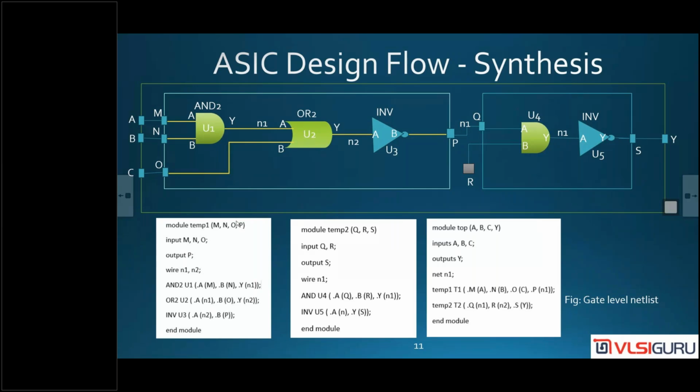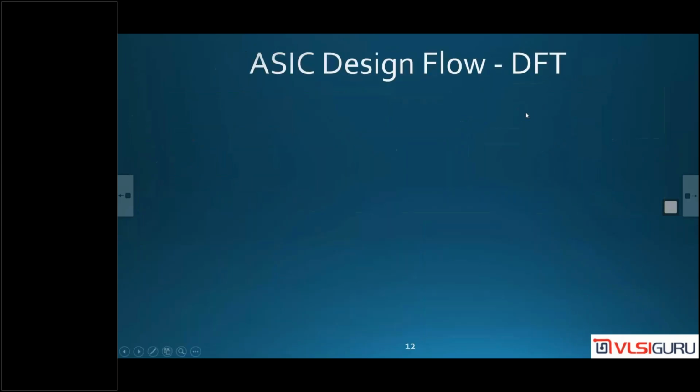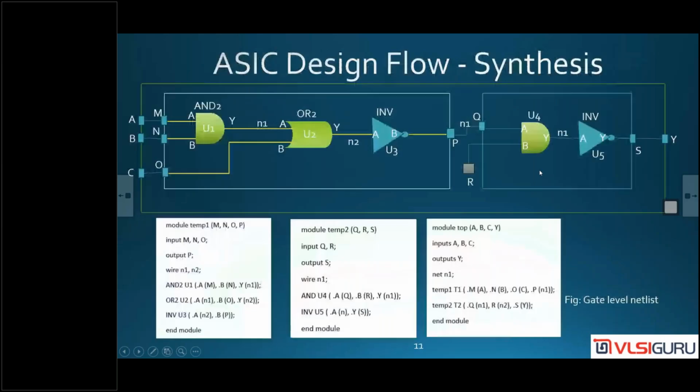So after synthesis, the next team that comes into the picture is called DFT, design for testability. Whatever netlist we have, this netlist is modified so that the chip can be tested after fabrication. See, transistors are not integrated. Transistors are inside the cell.